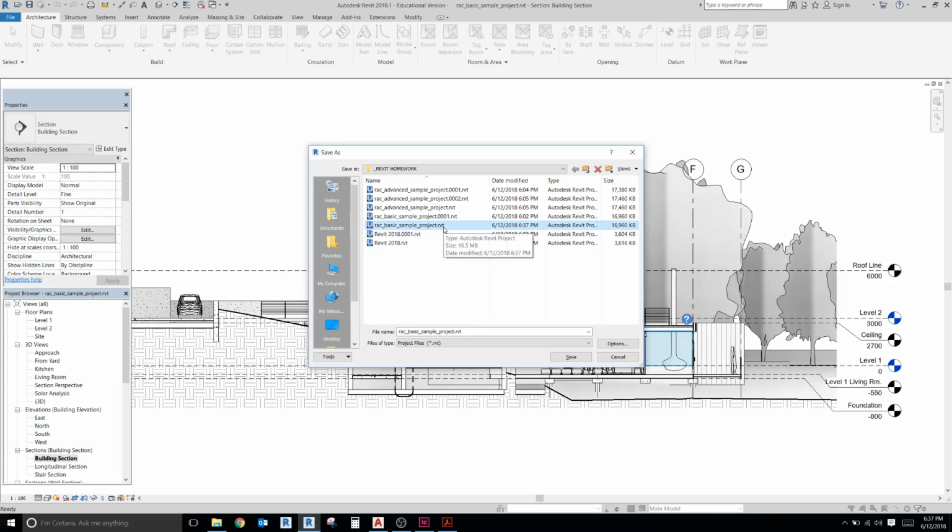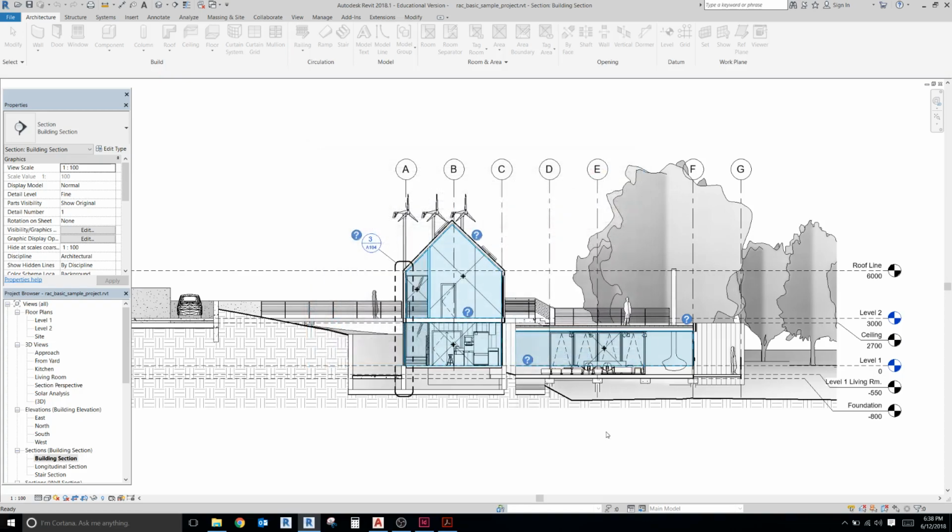I have a secondary type of file structure or file extension that I have when I work with Revit, and that's a backup file. It's also a .rvt extension, but it has a 4-number prefix before it. And then the final extension I'm going to worry about right now is an RTE extension. And an RTE extension is a Revit template file. I'm not seeing it here, but we will talk about that in a later section. This ends the definition of BIM software section.